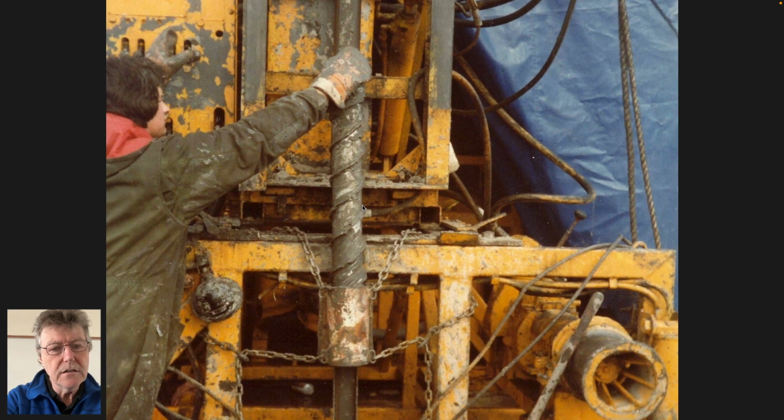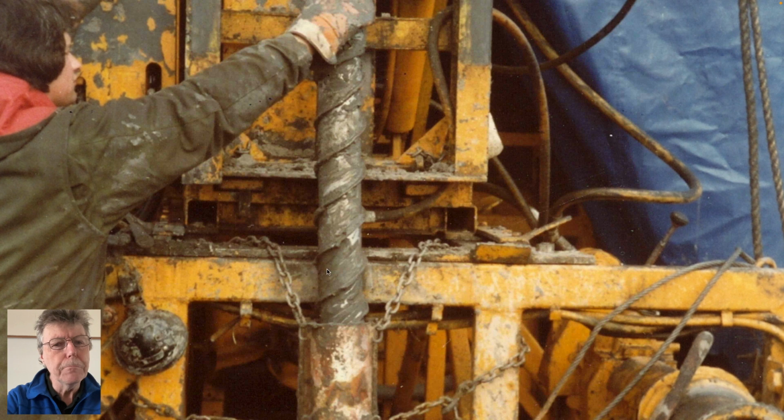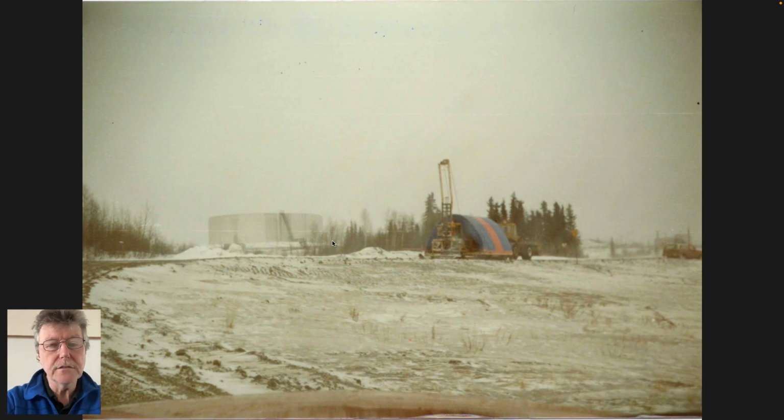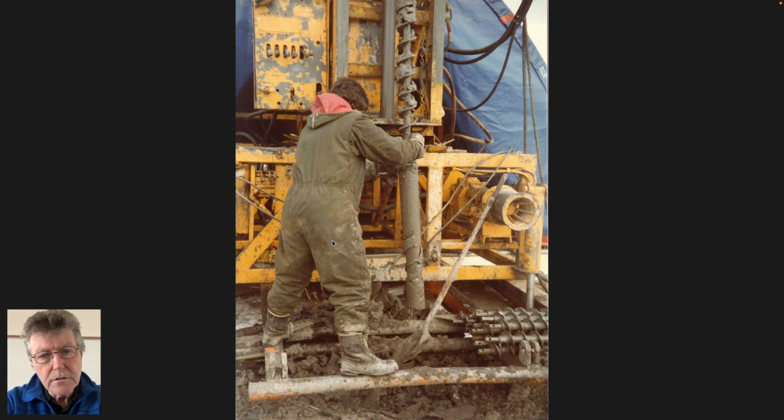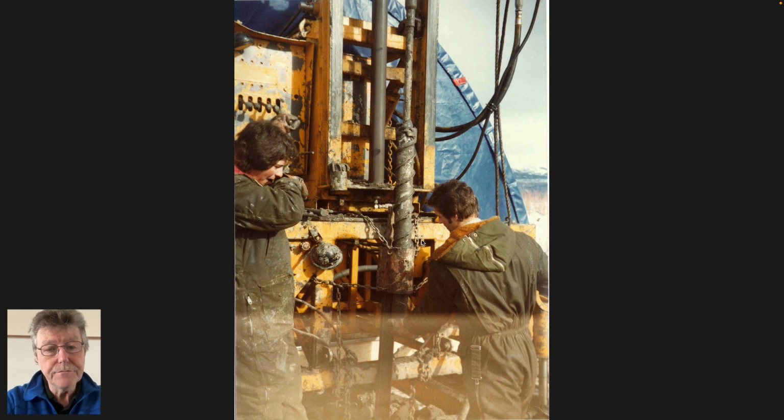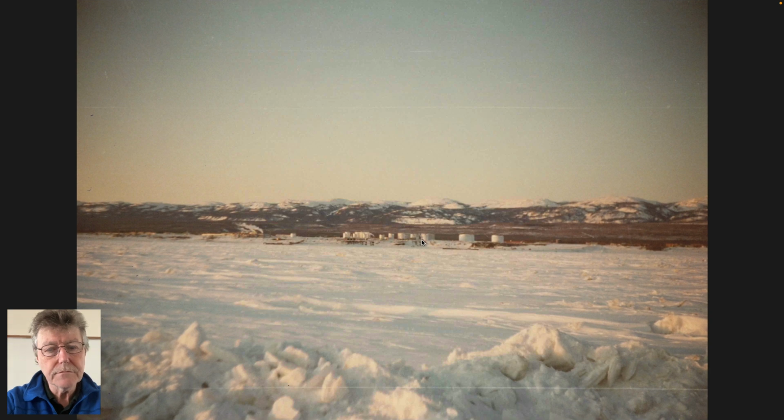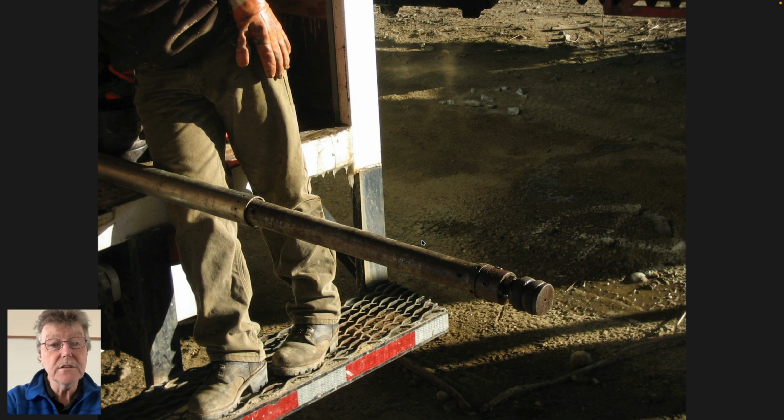And this actually is a core barrel. Actually, it's not. It looks a bit like a hollow stem auger, right, with a sampler going down the middle, but it's not. It's a CREL barrel, Cold Regions Research Engineering Lab. It's for sampling permafrost. So it's just a hollow tube, with cutters on the base which you can't see, and auger flights to ream the hole out larger, but it's for going through ice in this particular location. And that's it coming out of the hole. Norman Wells, Northwest Territories.